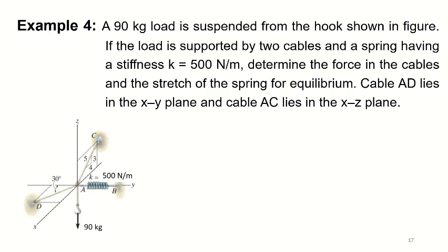Cable AC lies in the XZ plane, which means you can resolve the tension force in cable AC into X and Z directions. The component in the Y direction is equal to 0, right? And the spring AB is in the Y direction, right?